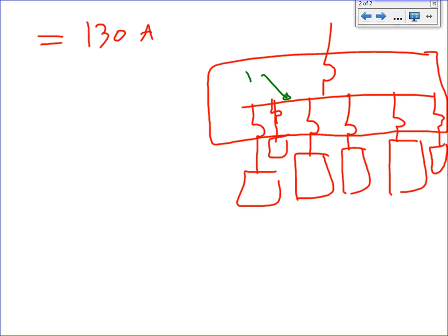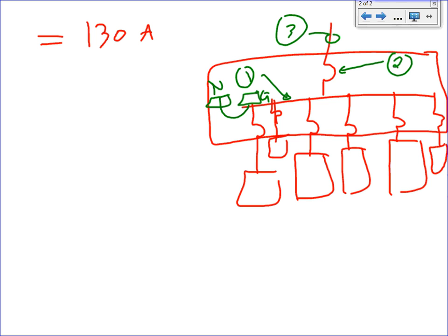Number 1 is the panel. Number 2 is the overcurrent protection device. Number 3 is the conductor. And since I'm going to drill that thing in your brain, guys, this is my neutral. This is my ground. My bonding conductor between them, that would be number 6, and the ground is going all the way to Mother Earth. That will be my 5. Okay? Like we did all the time, guys. We're going to size these 6 things for this system.